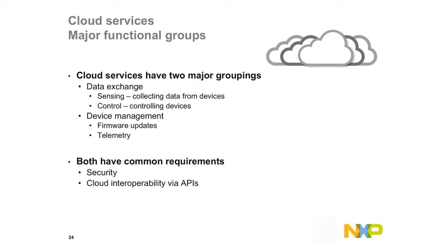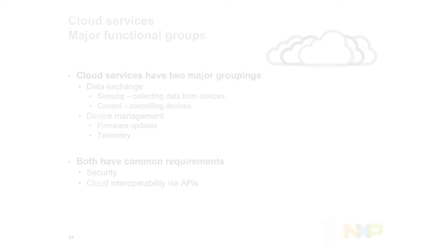There's another part of the cloud side of things, which is the whole device management. And this is the bit everybody doesn't think about. This is the bit where your security starts coming in. You've got to be able to do firmware updates knowing that this firmware is going to that product and not to another product, or that somebody in the middle is not hijacking and putting fraudulent software in. These are all very important things.